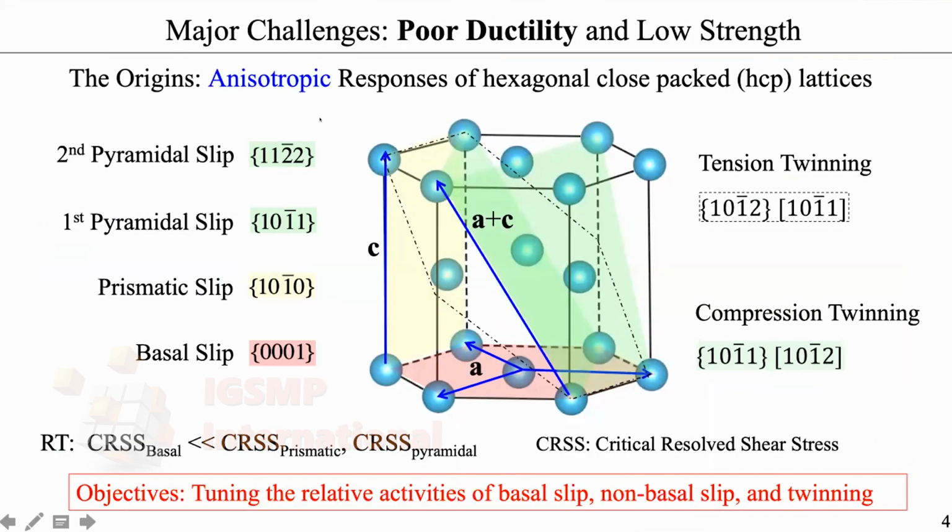Okay. So the poor mechanical property actually comes from its lattice structure. We go a little deeper in the material size, but if you look at the lattice structure, which I tried drawing here, it has the so-called HCP lattice, a hexagonal close-packed lattice. Such a lattice has an anisotropic response, which is very different from cubic lattices, for example aluminum and steel.